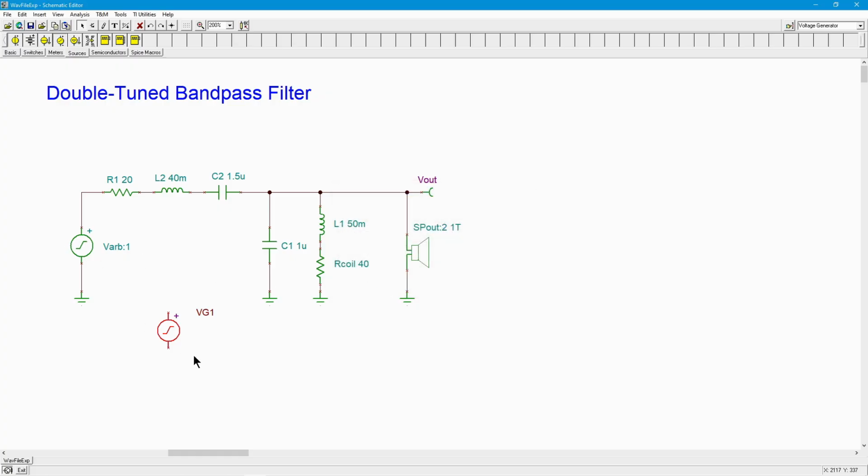So I've already done that with my arbitrary waveform generator. I've got about a 4.5 second snippet of a tune I wrote and recorded a little while back. So you can hear that. That'll be the input. Now, because that's a full range of instruments, at the output, here's our speaker output, we're going to hear that sort of pinched, thin kind of version because of this bandpass filter.